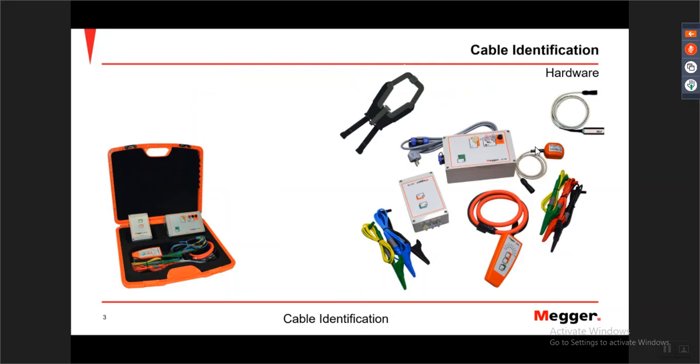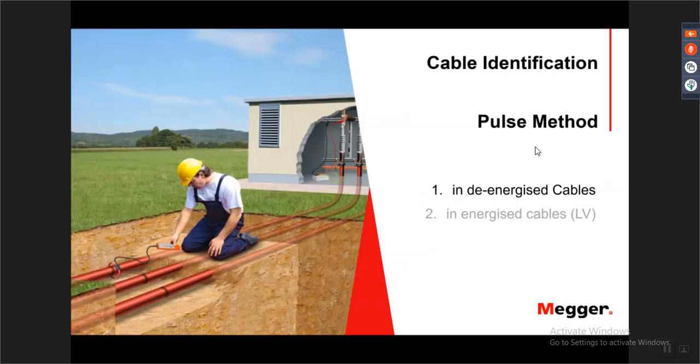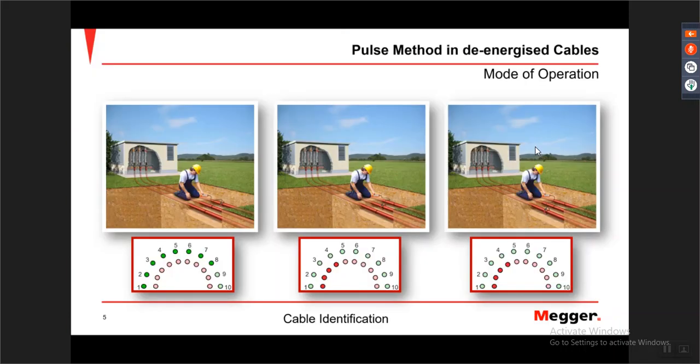So we look at the energised cables, the pulse method. If you look at picture number 1, the gentleman is on cable L1 and he is getting green positive lights. When he is on L2 in the middle picture, he is getting red negative lights, and in picture 3 on L3 again he is getting red negative lights. This positively shows that L1 has the generator connected to it.